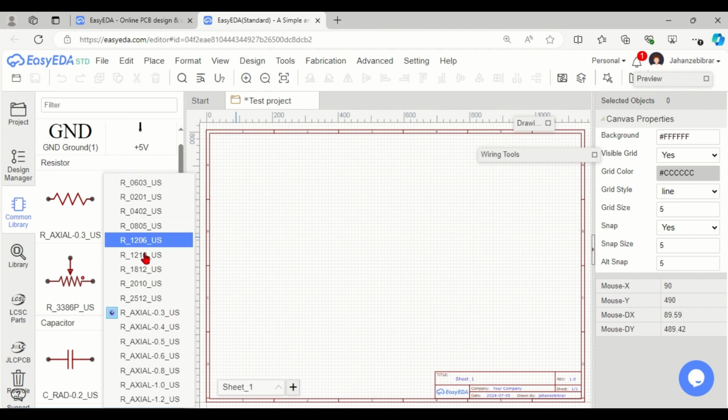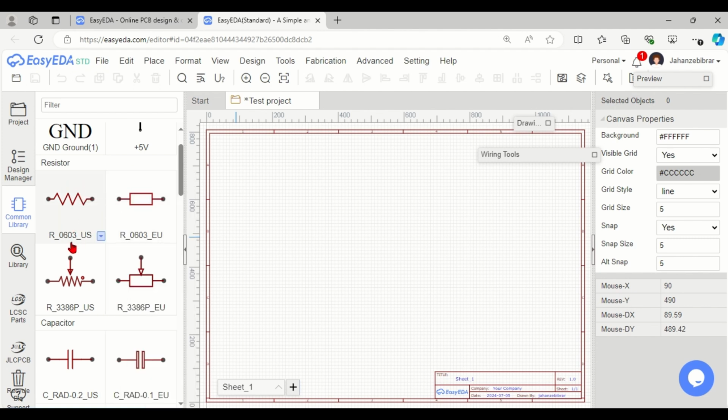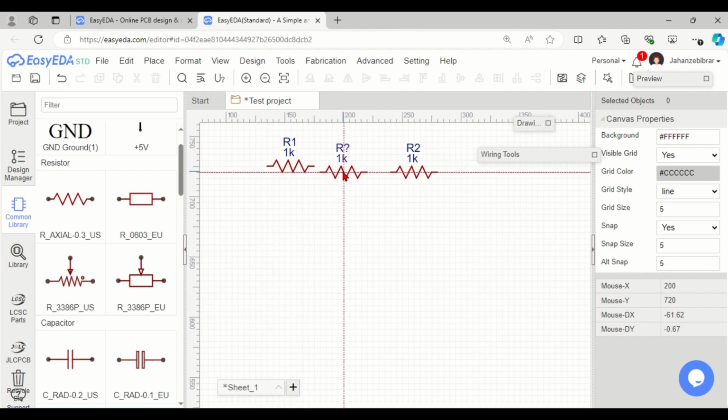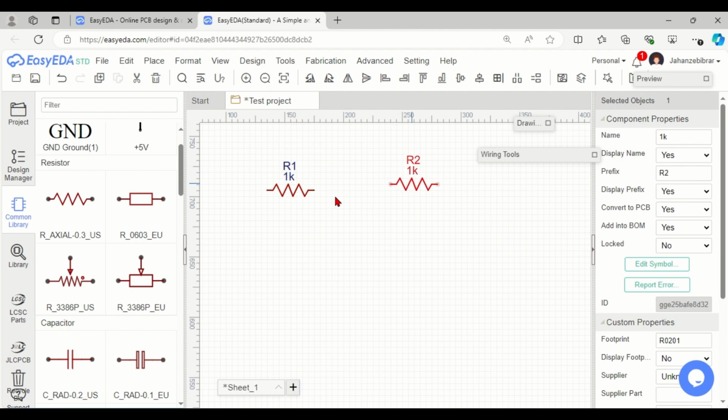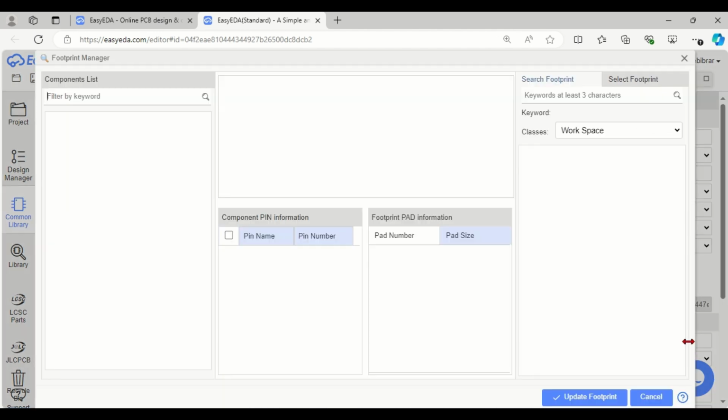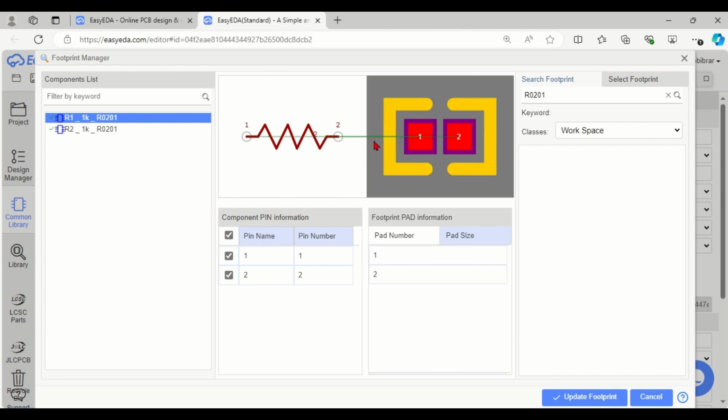These are all SMD components, so surface mounted devices. So I can give you an idea. Notice that if I select the part, the model number here changes. So if I place this component and I place this component, I can then compare between the two. Let's look at R1 and compare their footprints. So let's look at this component. Notice the footprint. It shows you that there are only two pads, and this is the outline for the component.